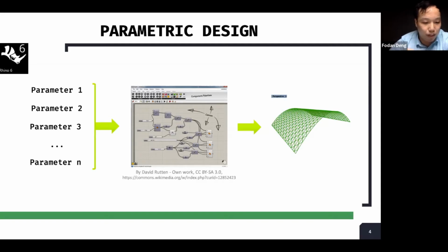If I only provide Grasshopper a 3, then Rhino can create a circle with a radius of 3 for me. So give a set of numbers and a set of Grasshopper components, then a geometry can be created. This way of creating geometry is parametric design.